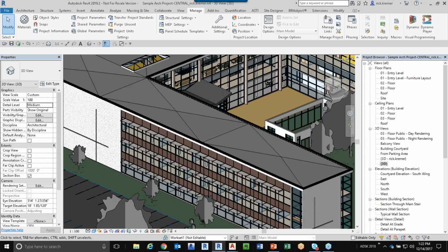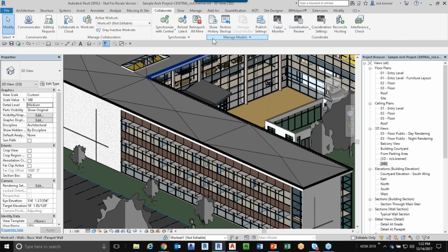And so that is basically some of my top recommendations and issues that I see when working with Revit files. Again, to go down those really quickly: correctly working with a central file. As a recap, you want to make sure to browse to that central file. Never open up the local copy. Then working with a corrupt file, we always want to go through and restore the backup.